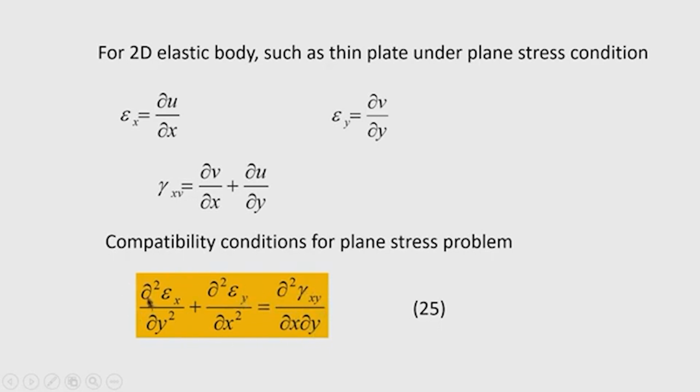Okay. So, in a mechanics problem, when you solve for a plate or any other structure, adopting any method, numerical or analytical techniques, finite element method or finite difference method, we should see that the equilibrium conditions as well as the compatibility condition must be satisfied. Okay.